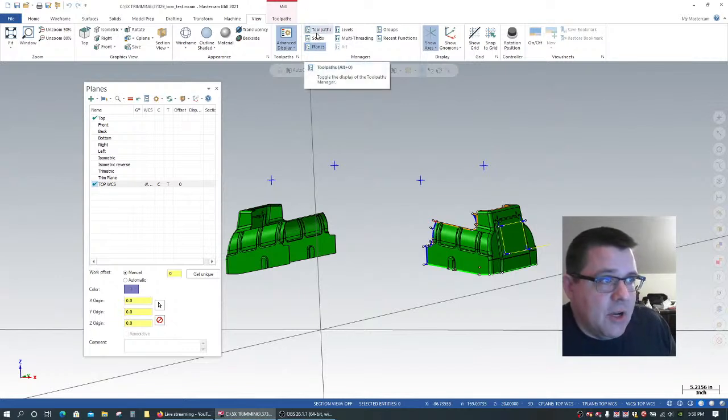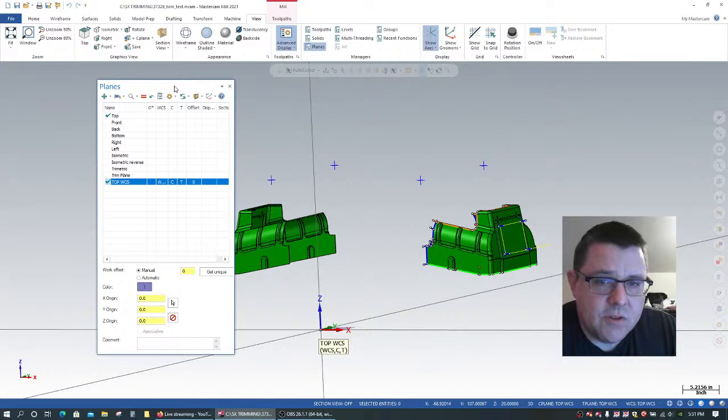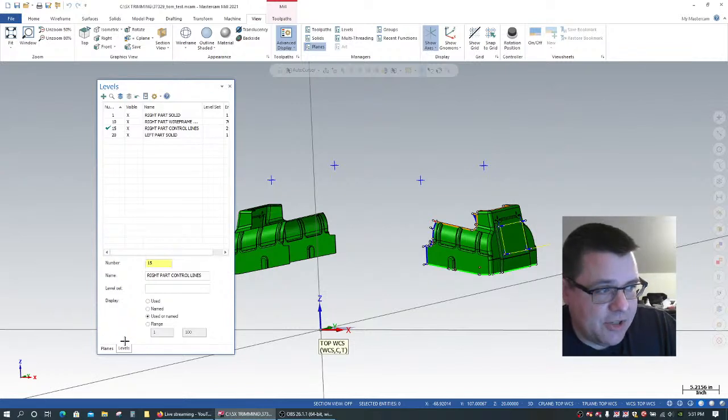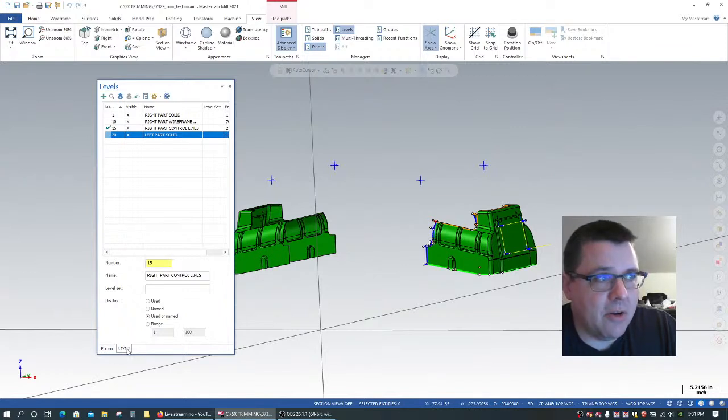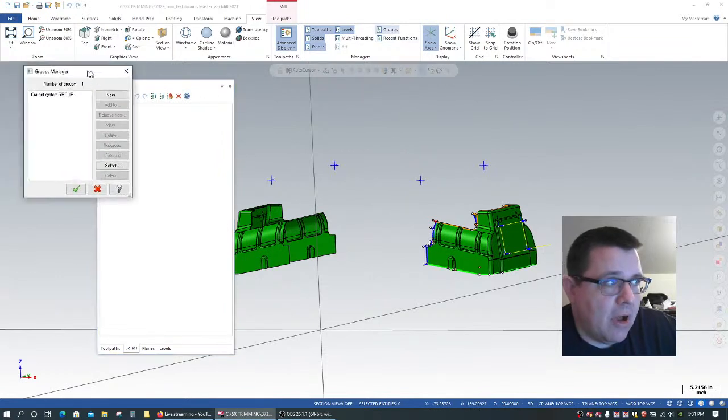So if you find that you've accidentally turned a panel off, so for example, the levels function panel, there's a toggle on the keyboard, Alt-Z. So if I hold down the Alt key and press Z, you'll notice that it actually turns on levels. It actually enabled that function panel, and you'll notice it's lit up here in the manager. So I can turn these on and turn them off. Like I said, normally I just leave them all on.